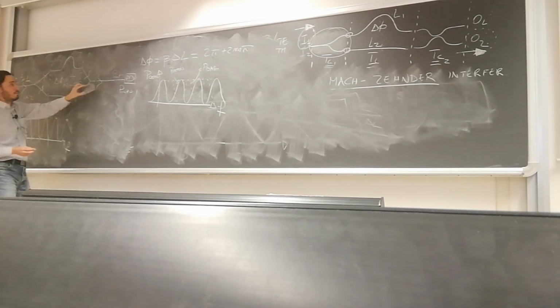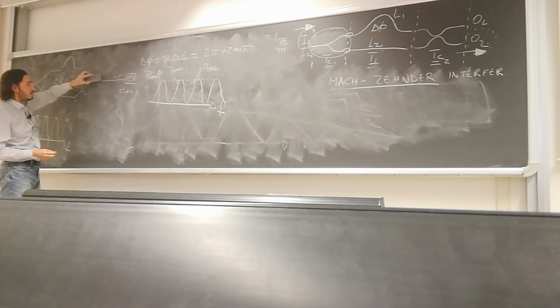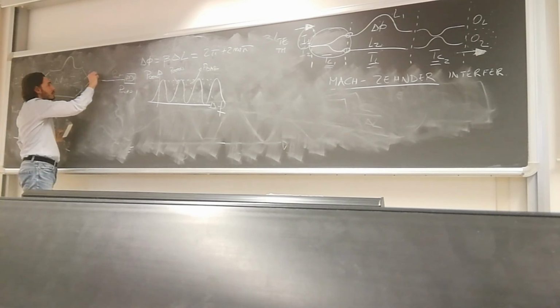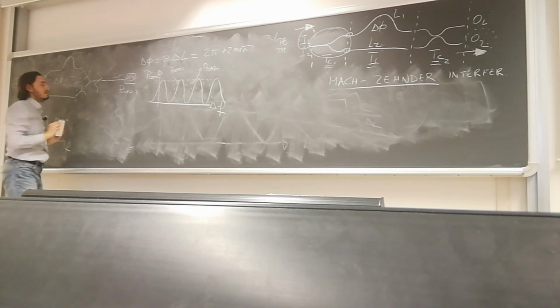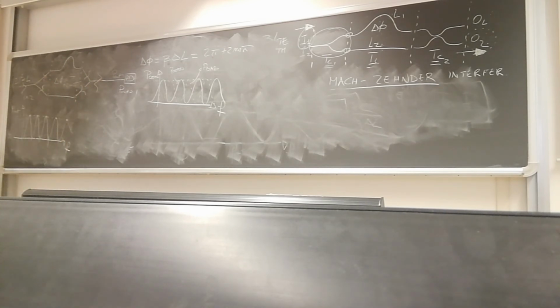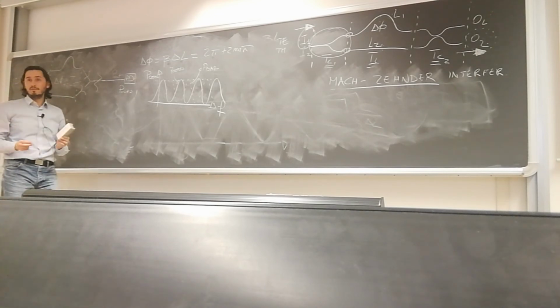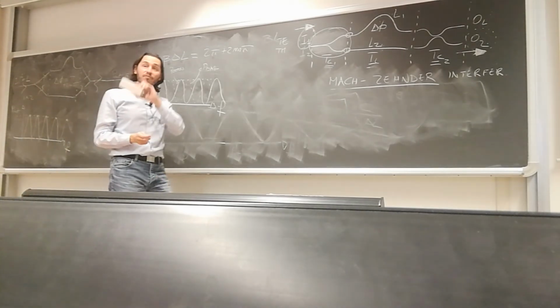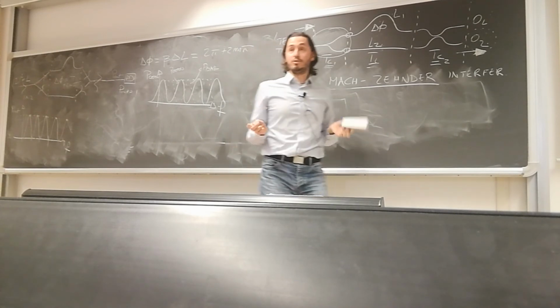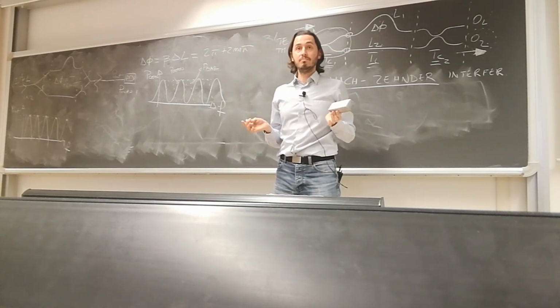And so I'm not going to excite anymore a field with an even symmetry, but with an odd symmetry. That is the sum of this plus this. So it's the second mode. And if this waveguide is single mode, it is radiated. If this waveguide is not single mode, this can survive.